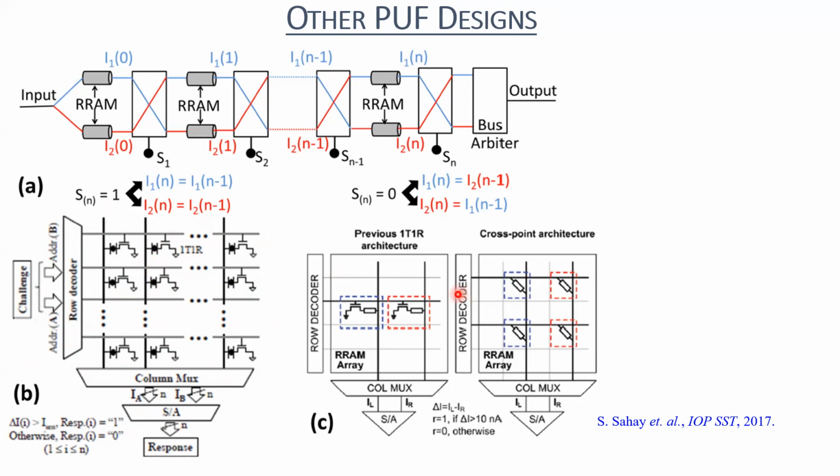The second, and I would say the simplest, architecture is similar to what I use. Here, people program their RRAMs throughout the array with the same programming voltage. And you know that the resistance value they attain will be different. So they probe one cell and compare its resistance with another cell, and that is how they generate the PUF. They can also generate the PUF response by comparing the resistance with a fixed resistance. That is also something people have already done.